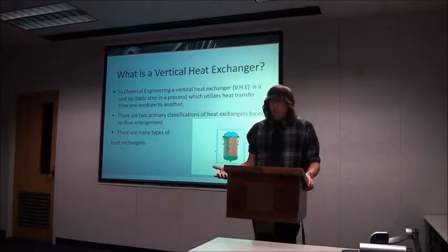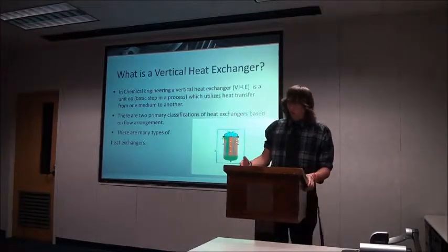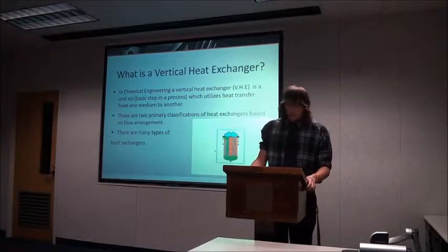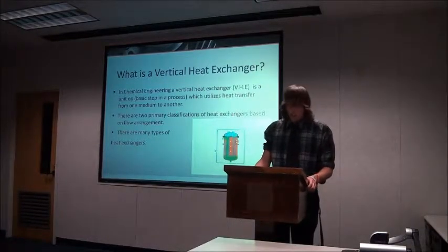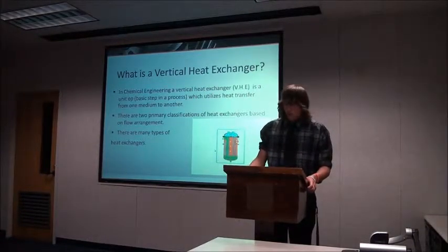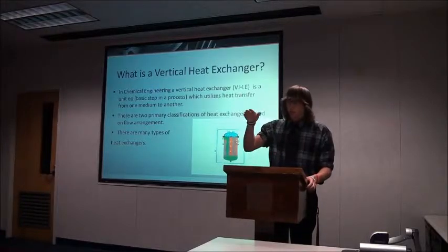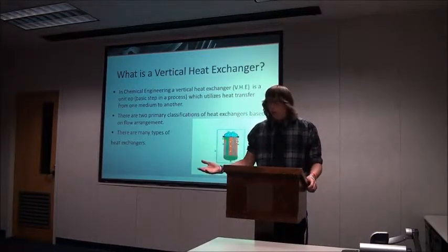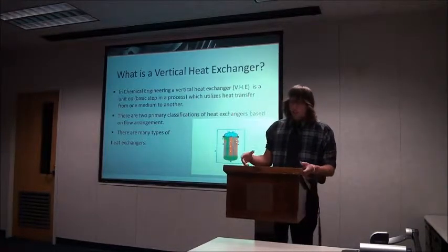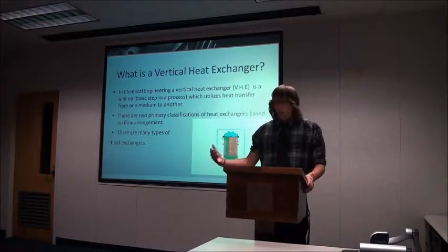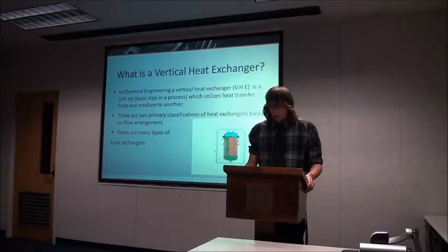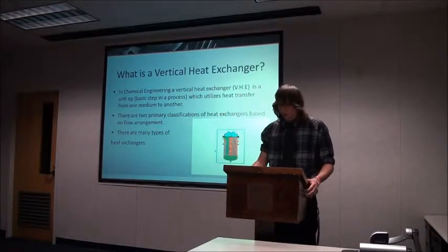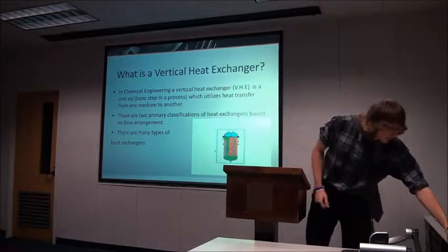There are also several different types of heat exchangers. I don't have enough time to go through all of them, but the basic one we used in the lab was the shell and tube heat exchanger. It is one of the most common ones. The heat exchanger consists of a series of tubes containing the fluid that you're going to transfer heat to or from, which is inside a shell where the second fluid flows over the tubes, causing conductive or convective heat transfer to occur.